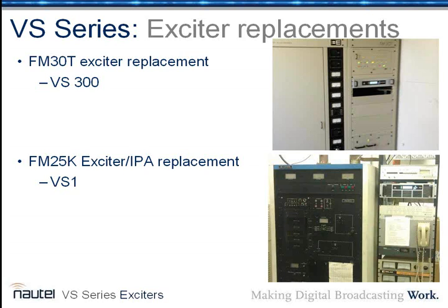Alex, how critical was the grid tuning to making the VS happy? Not very. It wasn't terribly difficult. The grid just came right up and said, "Oh, hi, look at you. You're pretty. I like you." It just turned right on. Like I said, it made the transmitter more efficient overall. Once the exciter and the IPA were pushing about 318 watts into the final. Right now, when we put the VS1 in there, we only needed 290 watts of drive.